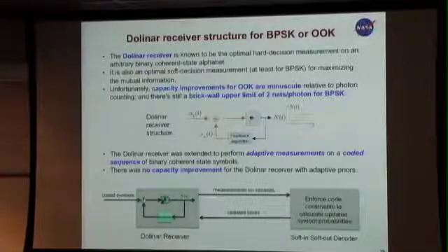But we thought, what if we had coded symbols rather than one, and kind of had a loop with one of our decoders, like we use for iterative decoding of LDPC codes or turbo codes, fed all this back, but the answer is nothing. We didn't get any improvement.